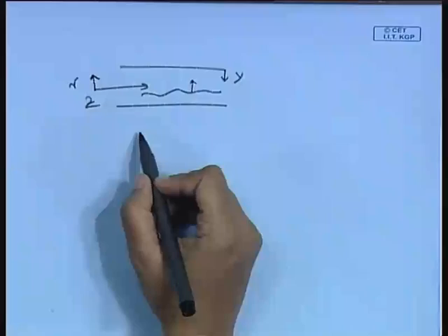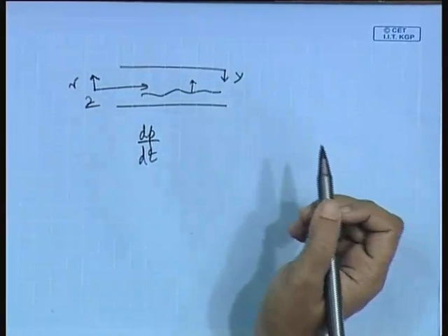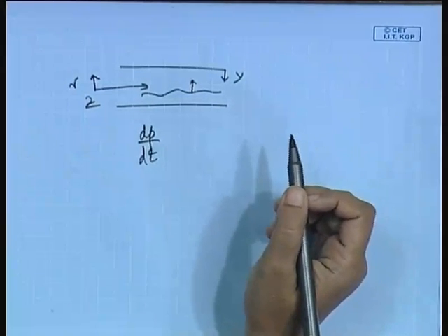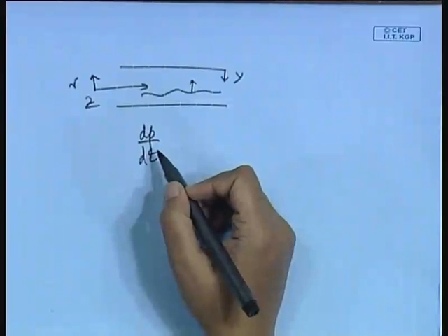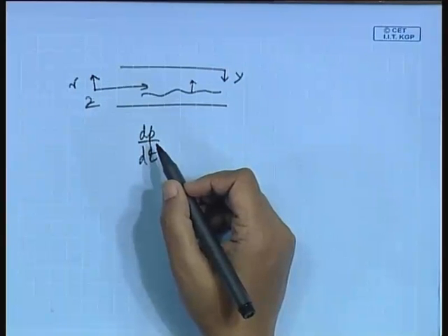Since this is the z direction, the rate of change of static pressure with distance is naturally dp dz, isn't it? You must have noticed that initially, when I did the momentum equation derivation for single phase and two phase, I referred to dp dz. The reason is simply this and nothing else. So, we mention the rate of change of static pressure with distance as dp dz.